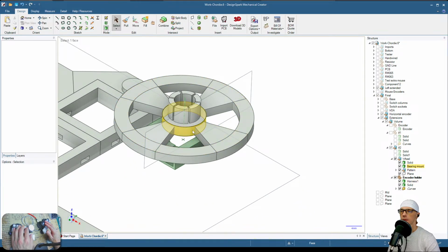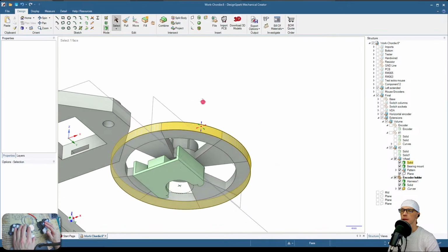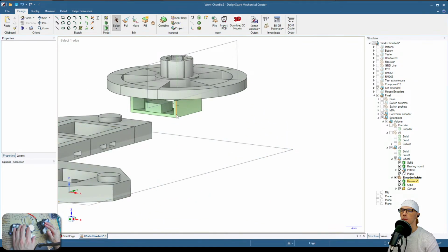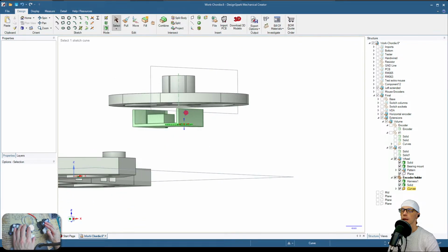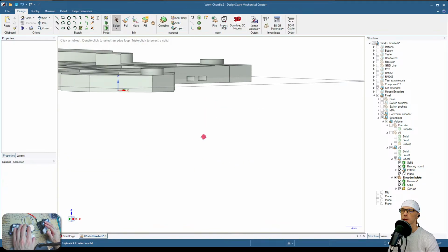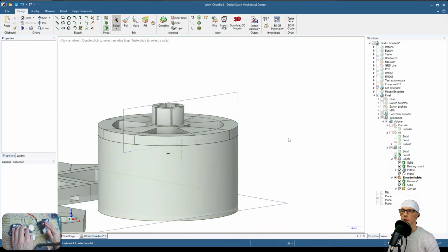Yeah, so I didn't have much time as usual, just a little bit of progress. So I have this top wheel. I have a piece of the encoder mount. I think we'll have to change it. I think we'll have to fill this hole because the switch will be somewhere over here. Or maybe technically we can move it a little bit down. No, it can't be fixed with this because this whole thing will be flexing. So the switch has to be underneath. And I think I have some kind of a column or something like this.